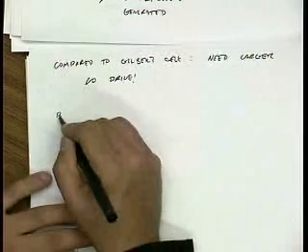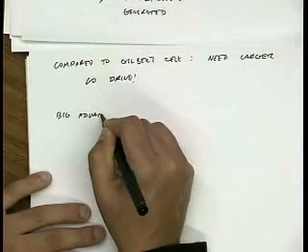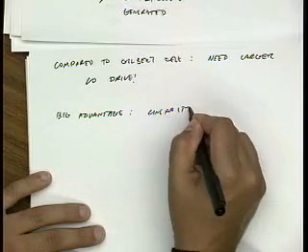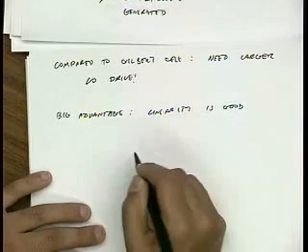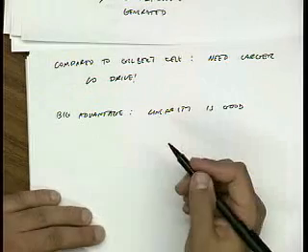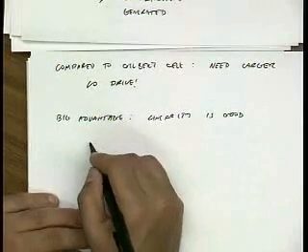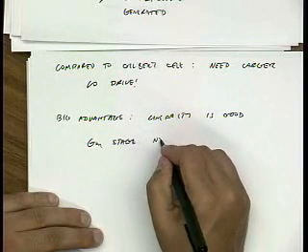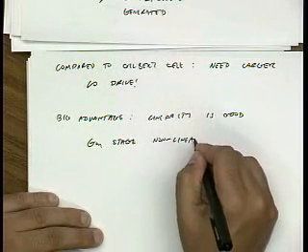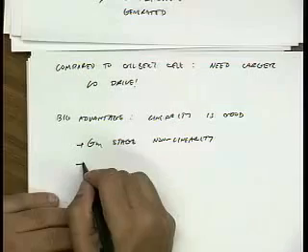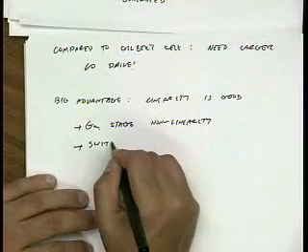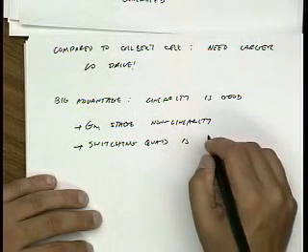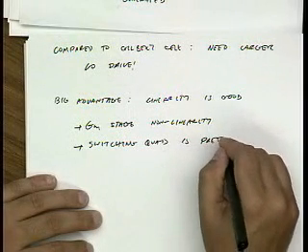A big advantage is linearity. That's because after you get past the GM stage, you have your GM stage nonlinearity, then you have your switching pair nonlinearity, or your switching quad, which is pretty linear.